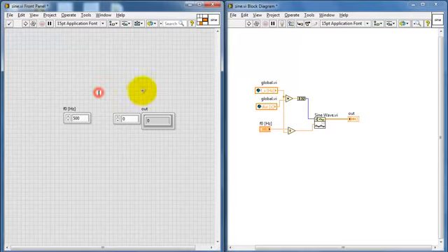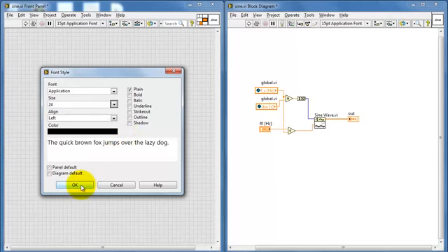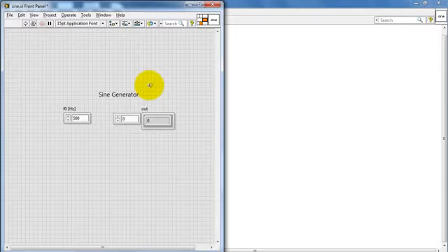I'm going to take this opportunity to also point out that it's good practice to include the name of the subVI, or at least some kind of indicator about what the subVI is trying to do. And it's also common practice then, well, let me make this a little bit bigger first. I did Control-0 incidentally to bring up that dialog for changing the font size.